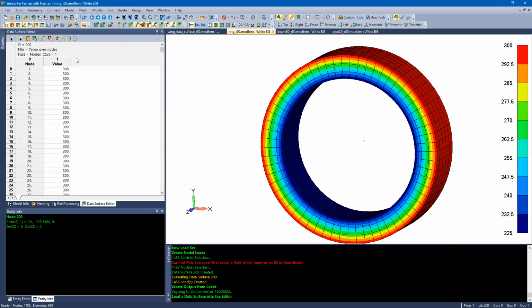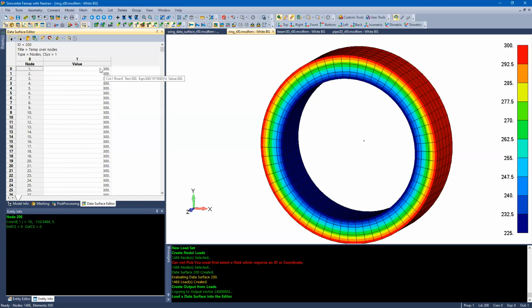And if I click on any of these cells, I can see there's a formula that I had typed in. So you can edit these formulas, then apply and use context sensitive to fill down. So you can basically change all these formulas if you want to. I'm going to show that real quick.